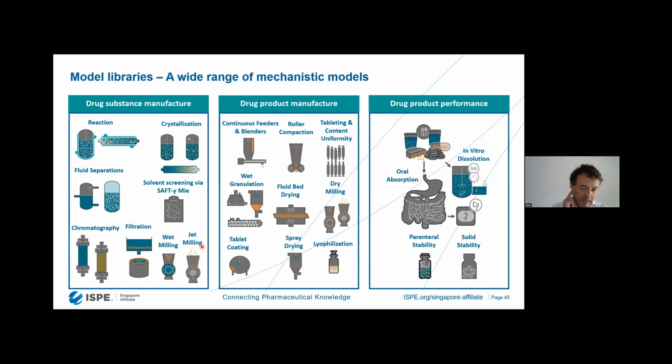But I expect it will become increasingly common, especially because the FDA is driving this as well. There are so many possible different disturbances that it is never going to be possible to test all of them on the actual equipment. So models will be used to look at many more possible disturbances and whether the process is inherently robust, whether the control strategy is adequate to deal with lots of different failure or disturbance scenarios.